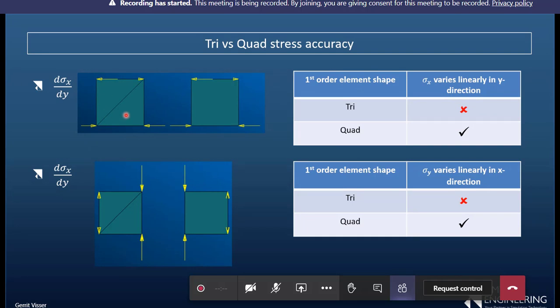So in terms of setting up the stiffness matrix and at the end back substituting, this will probably be slightly faster. In terms of matrix solution, they'll be exactly the same because they've got the same number of degrees of freedom. But if I want to model this bending, I'll get a horrible answer out of this and I'll get a really good answer out of this.